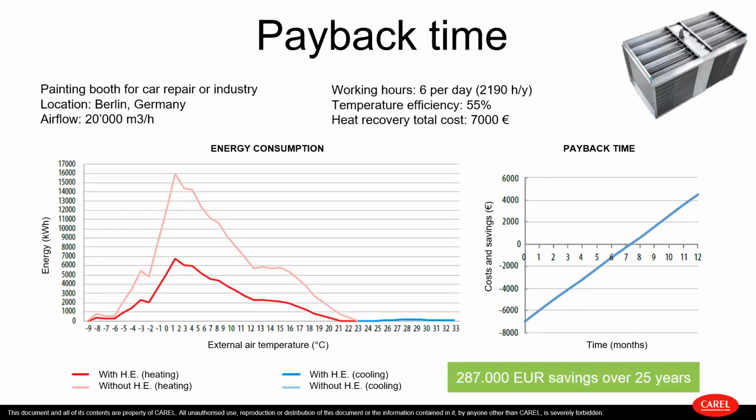This painting booth is in Berlin, Germany. The airflow is 20,000 cubic meters per hour. In the painting booth, people work 6 hours per day, so roughly 2,200 hours per year. Efficiency 55%, and the total investment in terms of increased cost because of the installation of heat recovery is 7,000 euros, more or less.